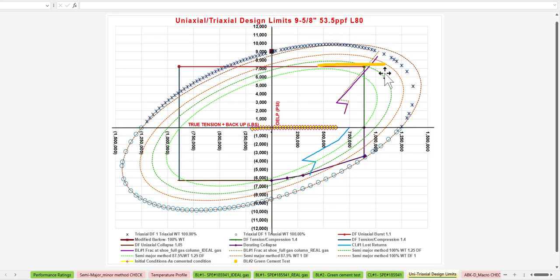And then here you have the tension. So you could see that from the initial conditions of 600, 650 with that 7,500 psi pressure, you increase your final true tension up to 1.078 at the top of the casing. So that gives you an indication of how much additional true tension you are adding.